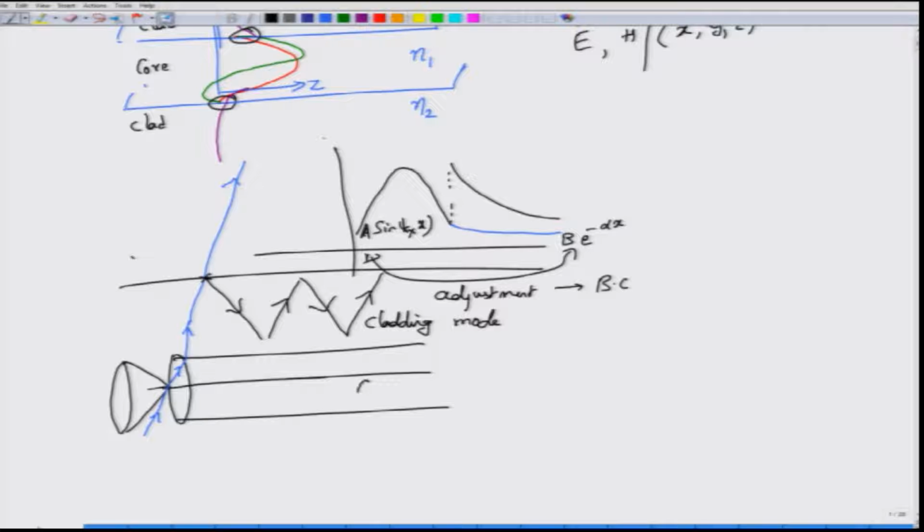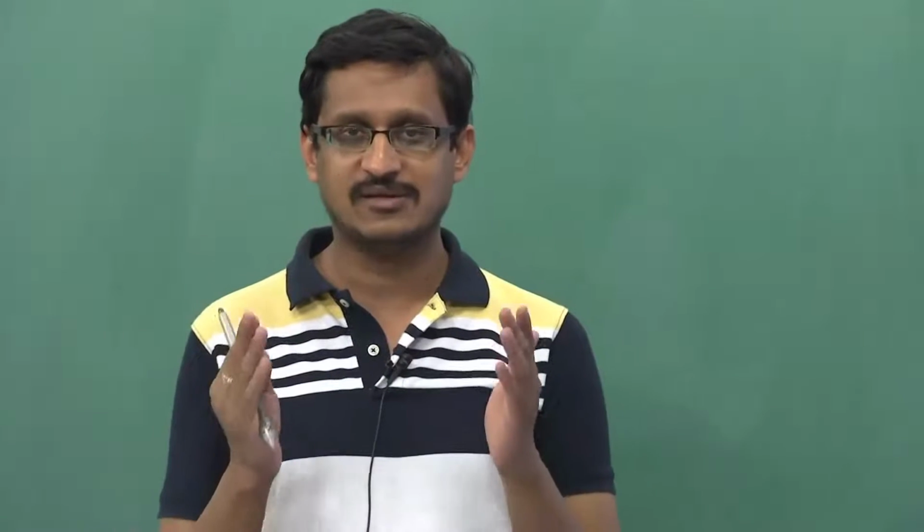Okay. What propagates inside the core will of course be core modes, or modes inside a core, and there is actually a coupling between the cladding mode and the core mode. So if by any chance I have excited the cladding modes, then these cladding modes will also propagate along with the core mode, of course at different group velocities, owing to the fact that the refractive indices are different and the propagation constants are different, but nevertheless they will start to exchange some power, which means that the power in the actual core mode will be stripped off into the cladding mode. So you see that there is actually a power loss in the core mode. So for that reason it is necessary not to excite any cladding modes, okay.